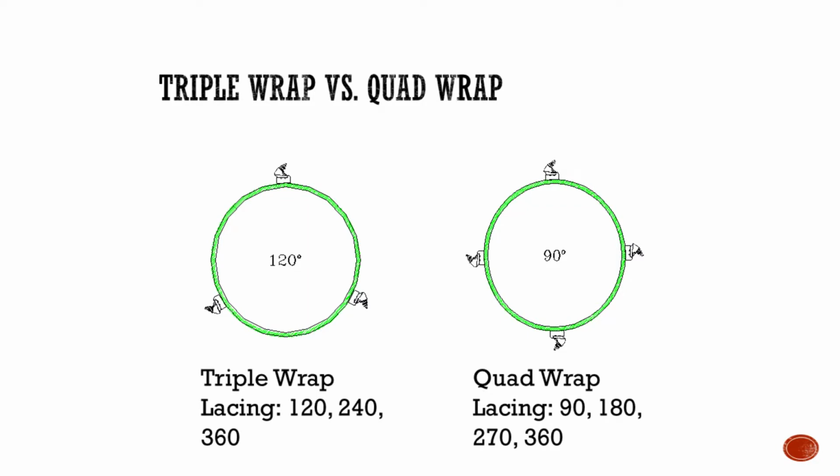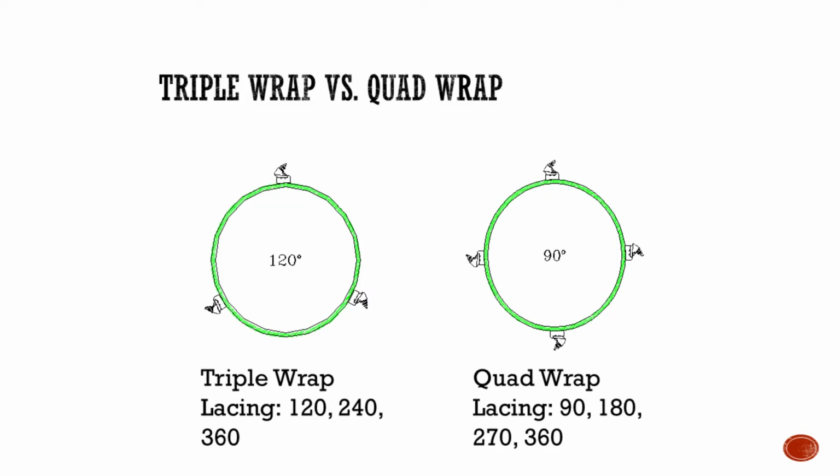What's interesting about the 4-wrap drum is you have a bit repeating. With the double wraps and the triple wraps, you'd have one single bit that is in the cut on any particular line at any given time. The 4-wrap drums, you actually have 2. So that longitudinal ridge that you would see in some of those patterns that would create that V mark, that second bit, that's 180 degrees, kicks that ridge down. So you're holding a more consistent pattern than a triple wrap drum when you factor in forward cutting speed.